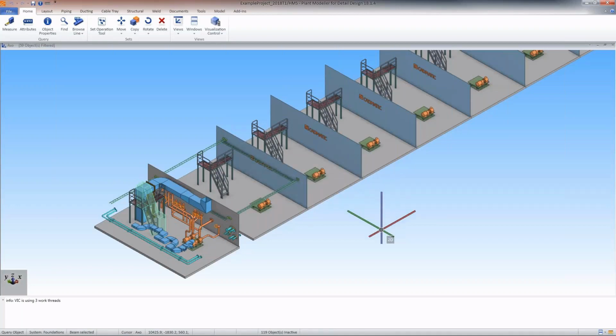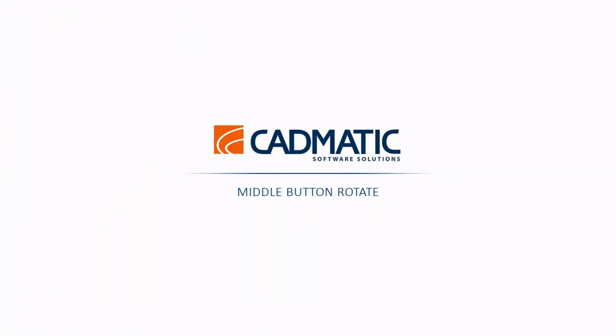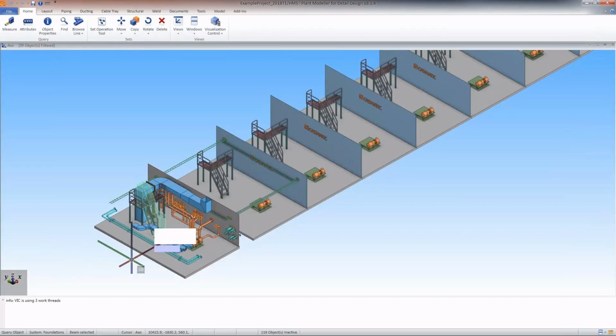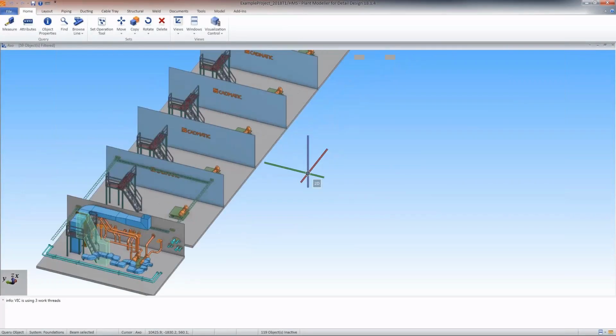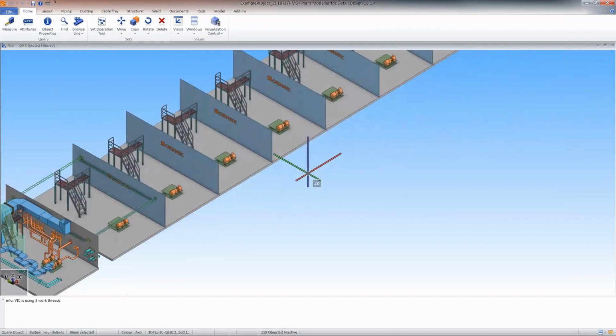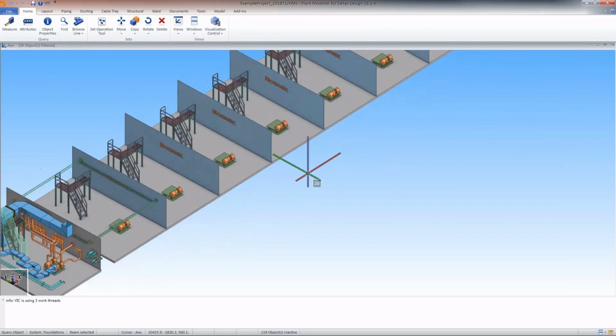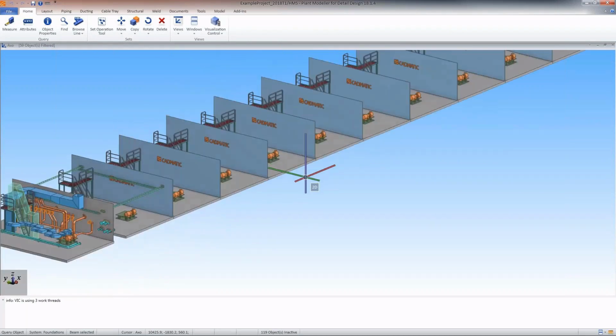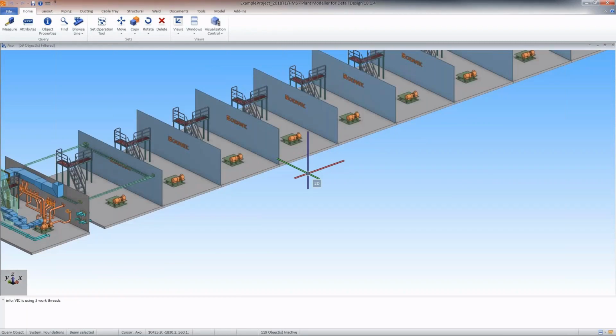Essentially, all the information that was previously available in the view's lower left corner is now also clearly shown on our cursor when we're navigating inside a view. The mouse's middle button also has some new functionality. Previously, we would rotate our axonometric view by scrolling while using the Control and Shift key modifiers. And these methods still work, but now we can simply click mouse middle button to enable rotating our view by moving our mouse.